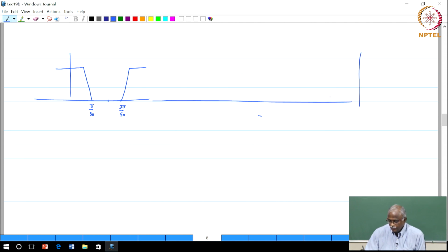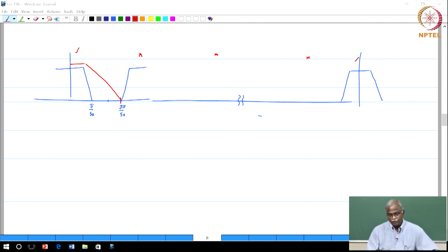Okay. And we just want to leave all of these and then go all the way to the last image. So, this has to be retained, everything in between has to be killed, right. So, I of z has to be a filter that does not distort you in the pass band and gets rid of everything beyond the stop band. Okay. And of course, it is a low pass filter. So, basically it kills all of the other images.